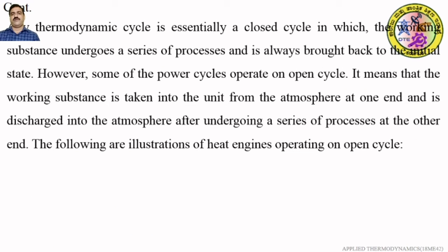Any thermodynamic cycle you consider, it is essentially a closed cycle. It means the working substance undergoes a series of processes and always returns back to its original state after performing its task. But there are a few cycles which work under an open cycle. It means that the working substance we use in the cycle is continuously absorbed on one side from the atmosphere, and at the other end it is continuously rejected after utilizing it in a given cycle with the various processes.